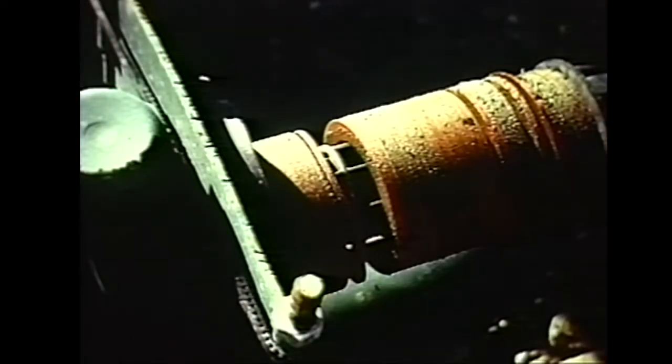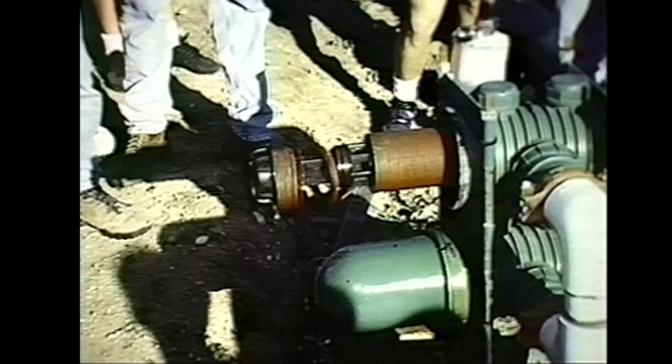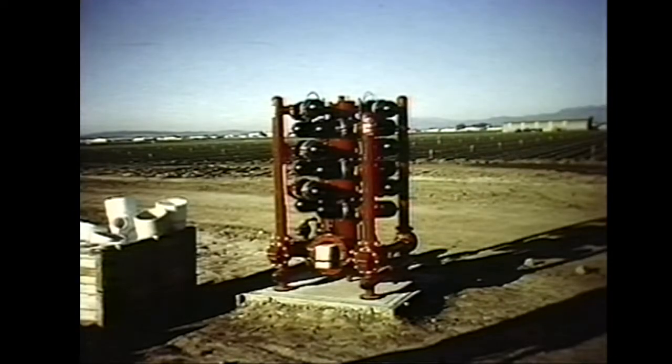Disc filters are best for organic matter. Sand tends to stick between the discs and sometimes is not removed during backflushing. Here you can see sand which has moved completely through the discs. If the system is not automated, the disc units must be taken apart, the discs separated, and then hosed off with clean water. Disc filters have the advantage of occupying a small space. Some units also come completely pre-assembled for simple installation.